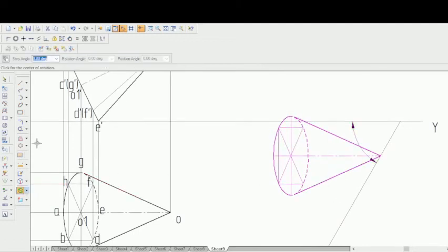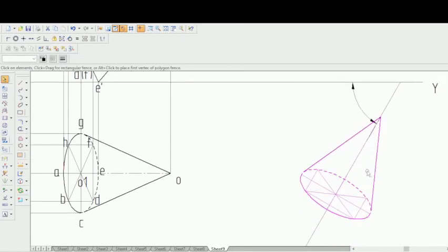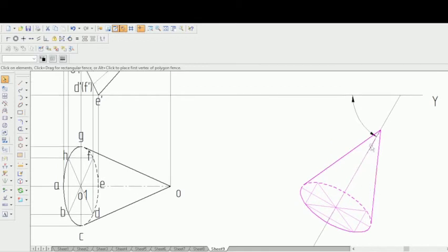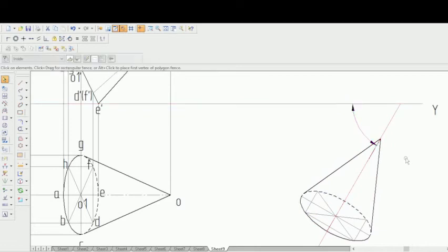Go to rotate. So that copy is switched off. Let this be the center of rotation, and let this be the point to rotate from. So let's try to here. Oh, that's fine. So now we have got it. So now, even if possible, if you want, you can try to move it a bit top, else you can try to leave it there.